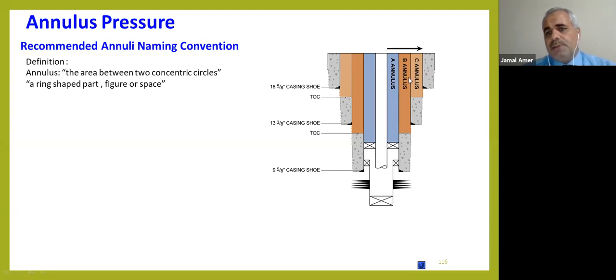It could be from the Christmas tree, or from the wellhead seals, either neck seals or cavity seals, or from downhole. Downhole, it could be from the reservoir. Here we may have bad cementing jobs, where the cementing is not good.